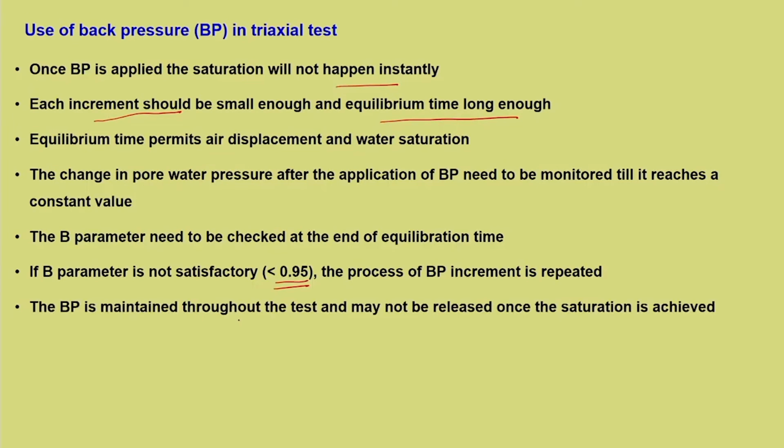So, the back pressure is maintained throughout the test and may not be released once the saturation is achieved. This is another important point: once the back pressure is applied, it is kept as it is. Once the B value is achieved, it is not that we close it. So, this back pressure may remain in the soil sample till the test is completed.